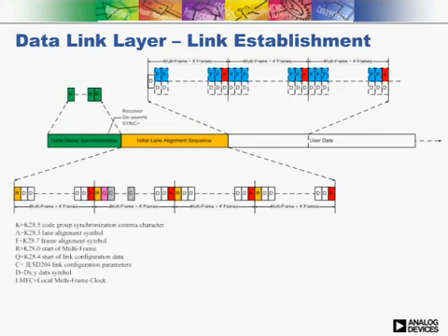So this diagram provides a visual representation of the link establishment procedure. The procedure begins again with the code group synchronization phase. Then the receiver would deassert the sync bar signal, initiating the initial lane alignment sequence, or ILAS. And once the lane alignment sequence is completed, the user data is then valid. And again, for the sake of time, I would encourage you to download the presentation and keep this diagram handy. It is quite helpful in understanding the link establishment.